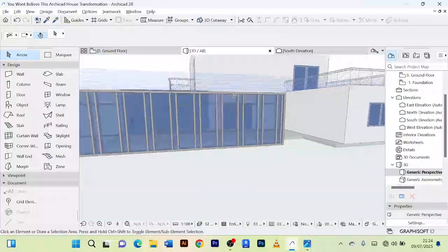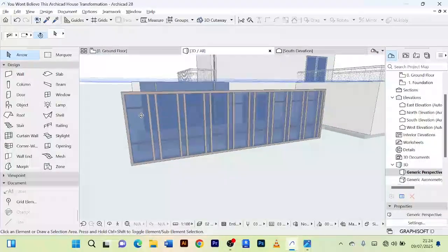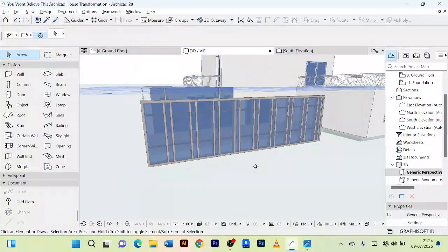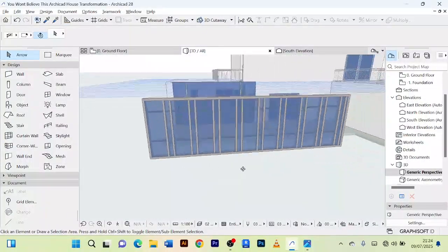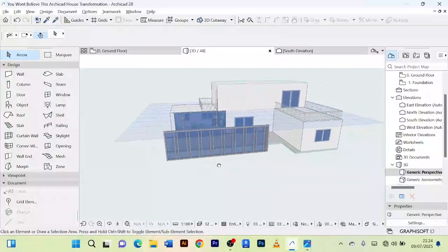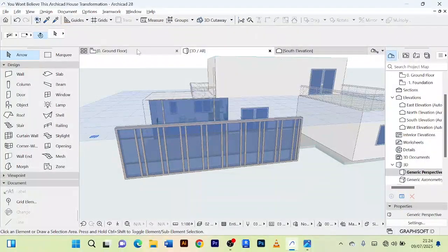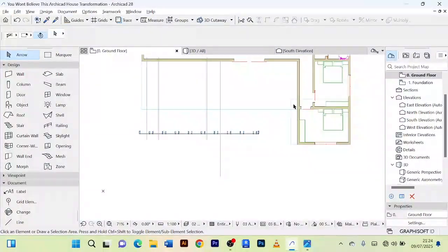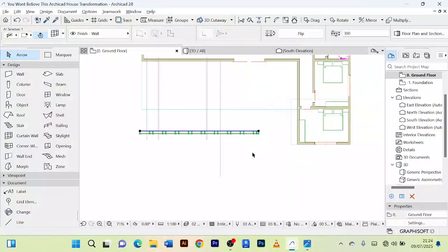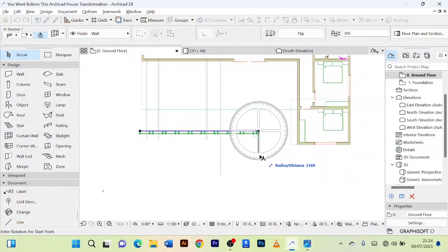You can either do this, change the materials and turn these things into glass, or you can decide to do what I did by basically creating the real curtain wall, and you change it. Now I'll just rotate this to fit in this wall. First of all, there's this part for flipping. Let me see what we can get here. That's okay. Then I think I can just press Control R to rotate it.